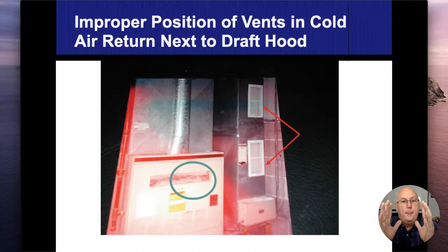Then that blower fan depressurizes that ductwork and causes it to collapse. And usually the fan builds up speed slowly, so the sucking in part is not as noticeable. But then when the fan turns off, you hear that big whoomp, and that's all the ductwork coming back in there.